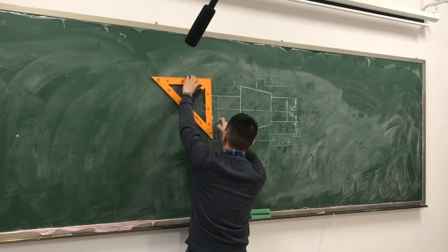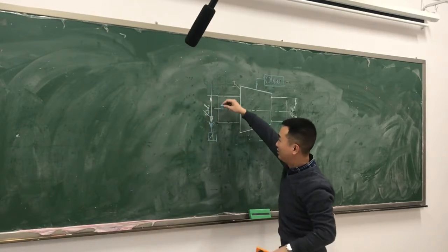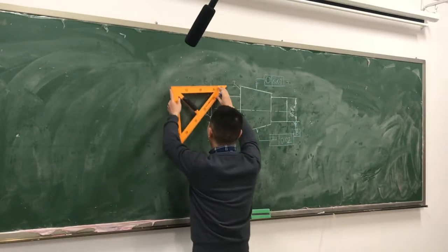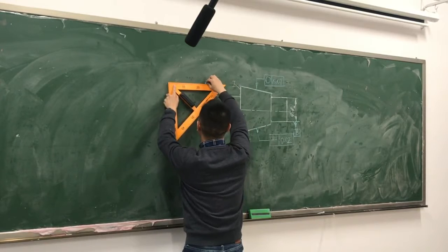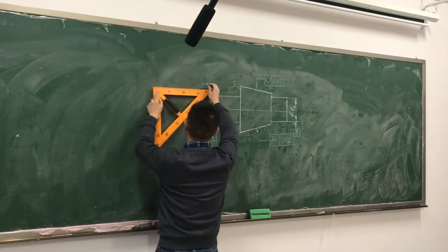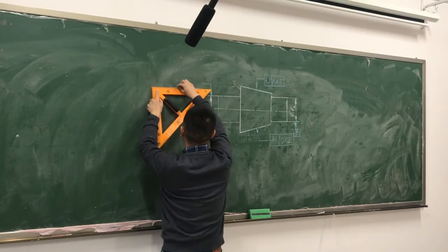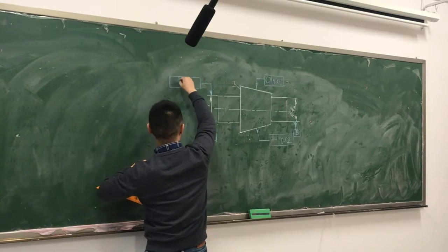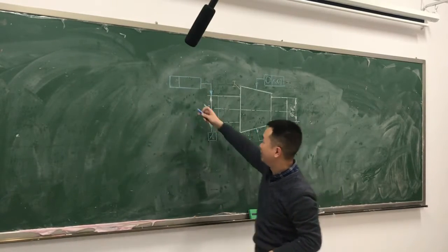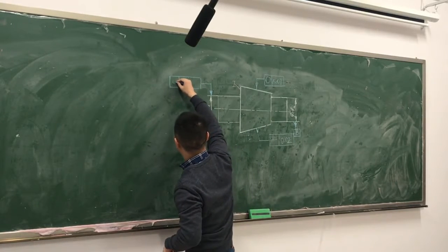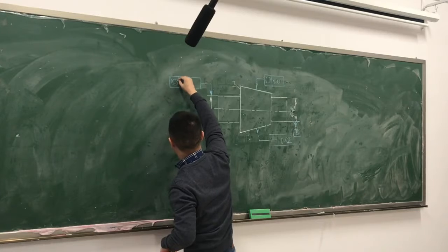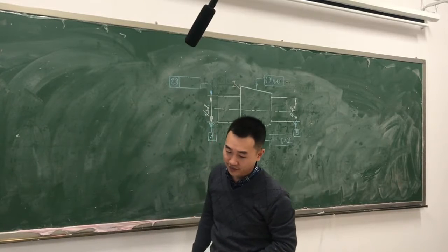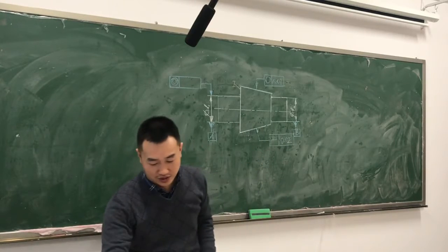So we need to put the lead line at the extension of the dimension line here, and try to label here. So we need to write down, here is the symbol. The symbol is two concentric circles, right? This means the concentricity. And here it gives you the tolerance value.